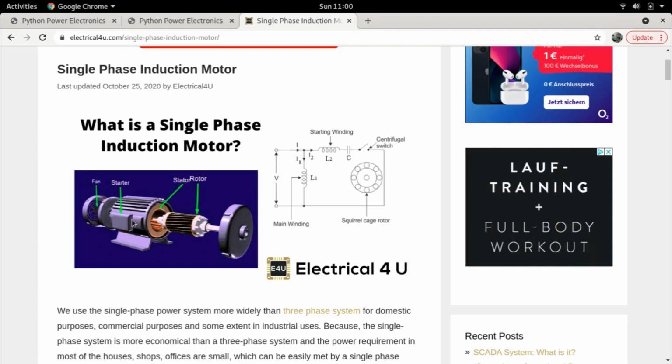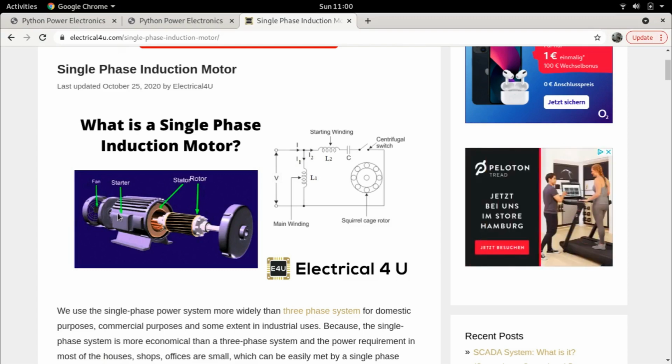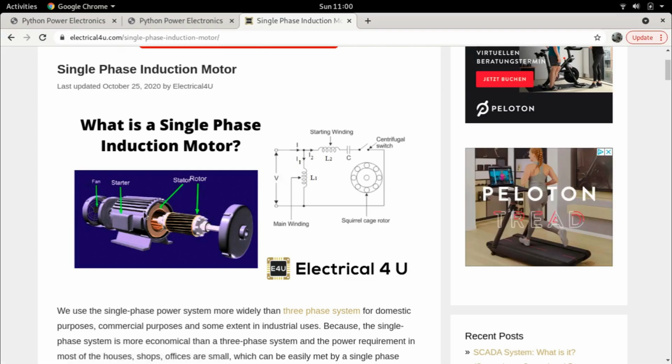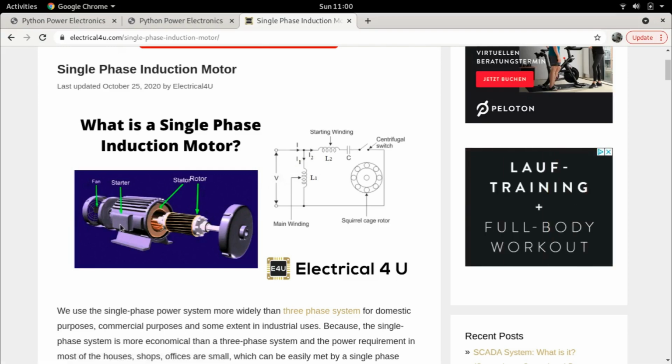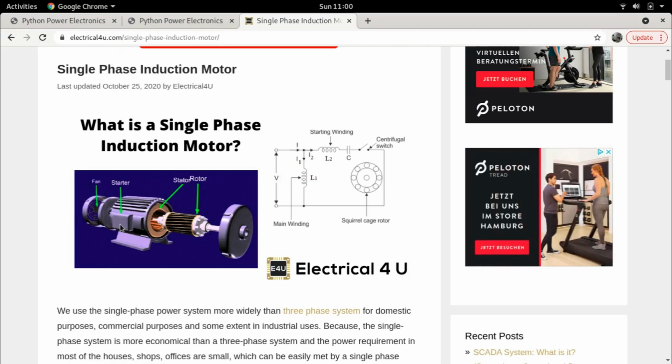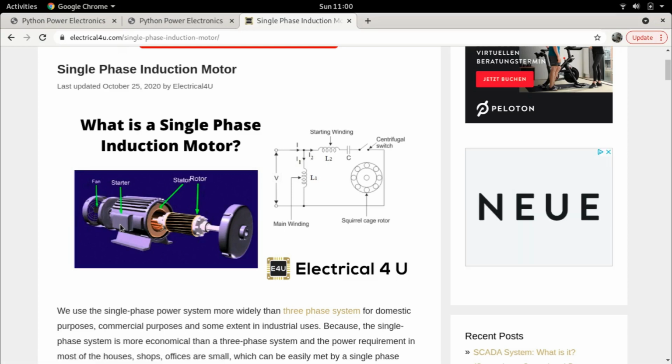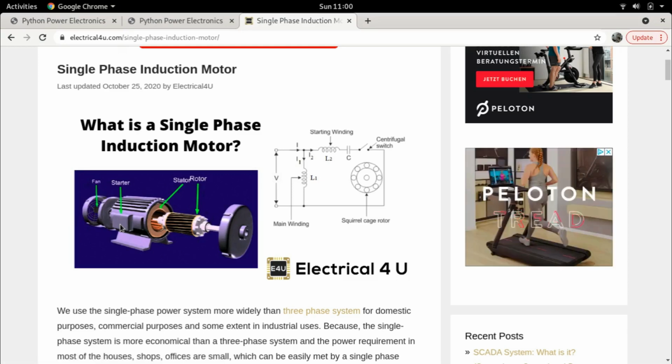And this effect on the motor is typically the applied voltage, right? This voltage, which is a single phase voltage applied to the stator of the machine, is the independent voltage. This voltage, though we choose it as a sinusoid, can have certain fluctuations. It can have spikes, it can have sags, there can be changes, there can be flickers. And all these changes will have an impact on the motor.